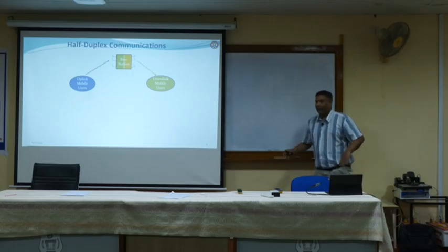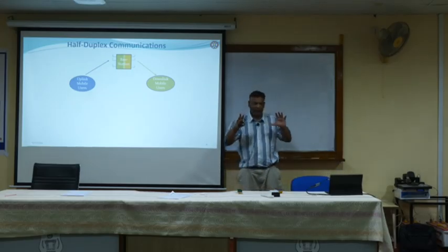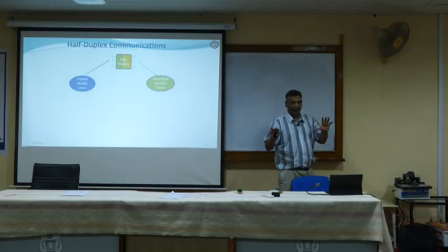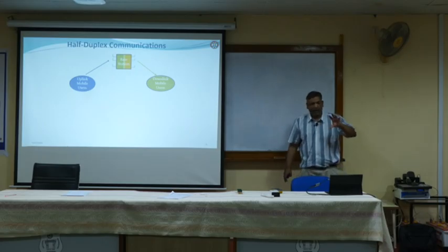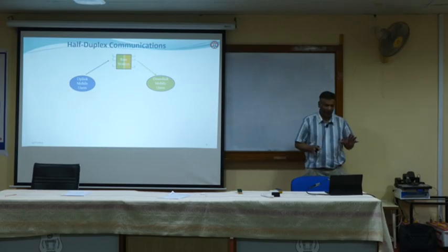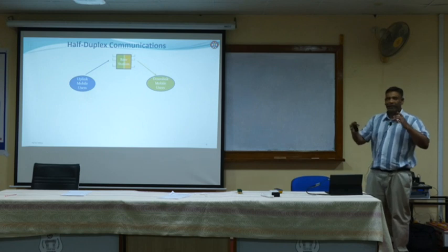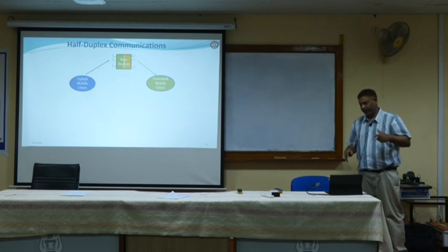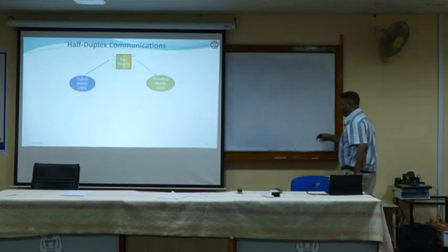Currently, all the commercial communication systems are operating in half duplex mode. I told you about that yesterday as well. Half duplex mode is the one in which all communication systems currently operate. That means the uplink and the downlink communicate in an orthogonal fashion. One is TDD, the other one is FDD. These are the 2 fashions in which uplink and downlink communications happen.